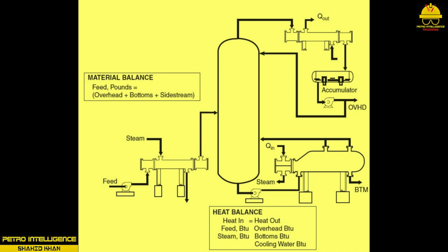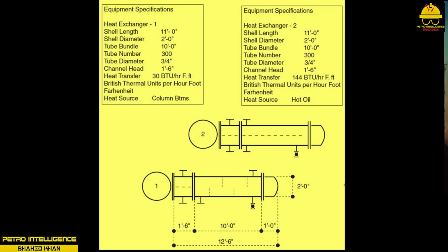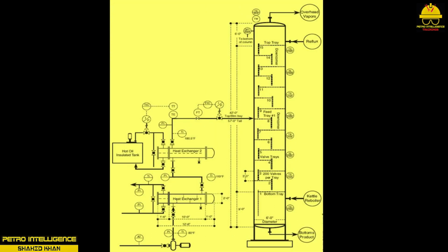Through the principles of conduction, convection, sensible heat, latent heat, and others, heat transfer occurs. Flow rates measured in gallons per minute are exposed to hot oil or steam that transfer energy through solid walls and into a moving fluid matrix. As these materials enter a distillation column, the pressure of the liquid being released on the feed tray or through the feed distributor immediately gives up heat energy. This heat needs to be sustained and controlled. These pictures show the detailed specifications of a heat exchanger and a preheat system.